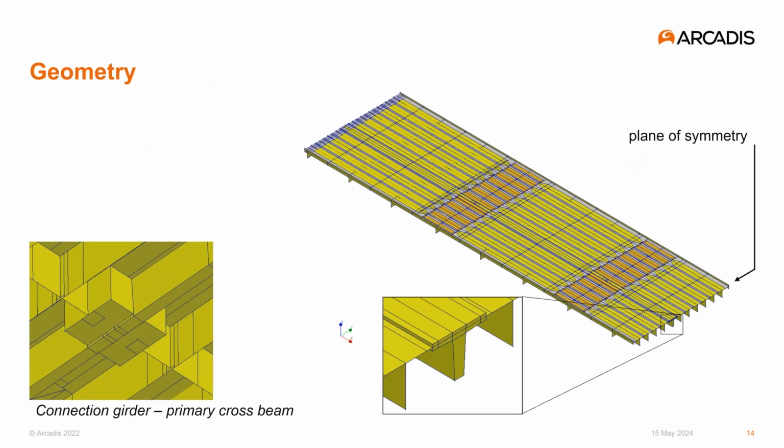As said, we modeled the 5th girder from the left side with solid elements and all other parts with shell elements. The pictures show how the solids connect to the shells. The right picture shows this connection at deck slab level, and the left picture shows the bottom side, where the solid parts of the crossbeams connect to the neighboring shell elements. So here you see the onset of the crossbeams and where they continue as shell elements. And this picture also shows the imprints that we used to apply the supports at the original and at the final positions.